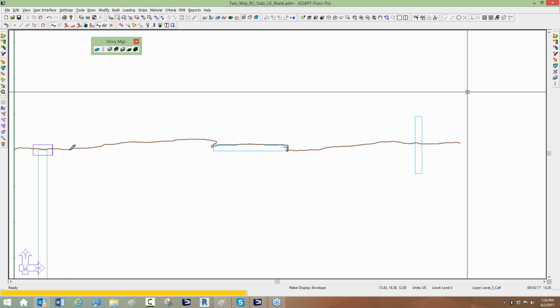We have a support line that extends over the wall, and we might actually add a support line just to the side of this main support line. And by doing that, we might have splitters that cut up to the next support line, below to the next support line. But what happens in this case is the tributary region over the actual wall becomes very small, it's basically this. This is the tributary region over the wall.